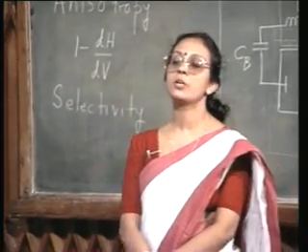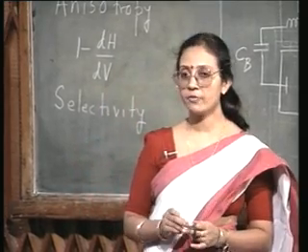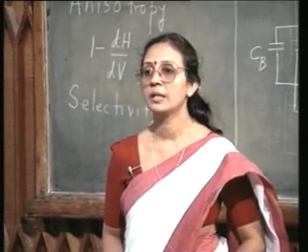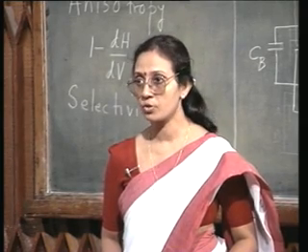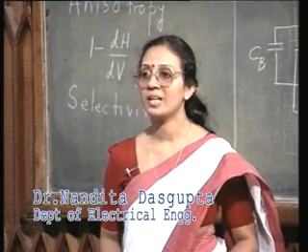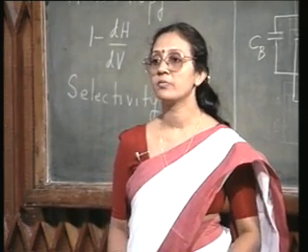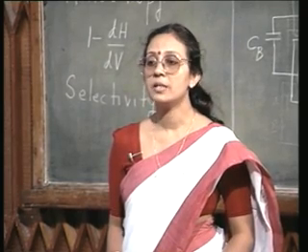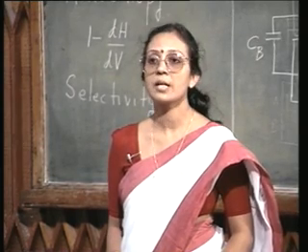Now, why am I harping on this ion bombardment energy? Because I have introduced the topic of dry etching by telling you that there are certain limitations of anisotropy in the case of wet chemical etching. So, obviously, one prime reason for moving towards dry etching is to realize perfectly anisotropic etching, and ion bombardment is going to help us in realizing a highly anisotropic etching system.